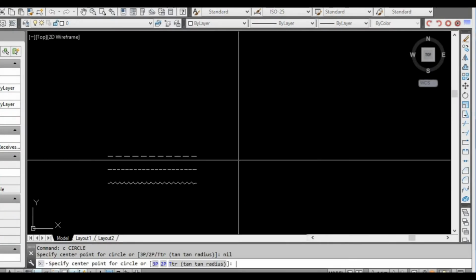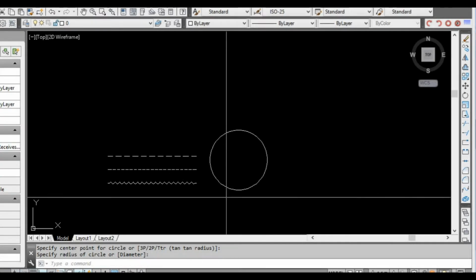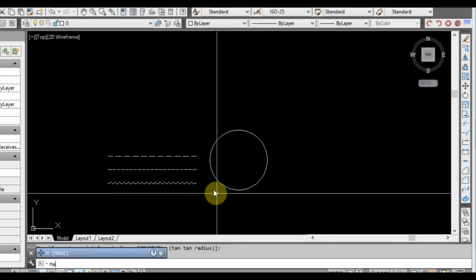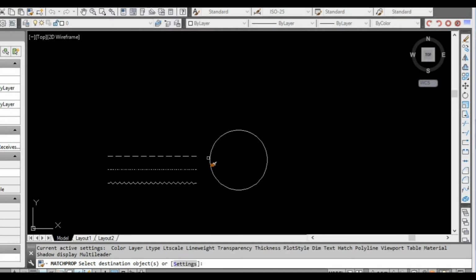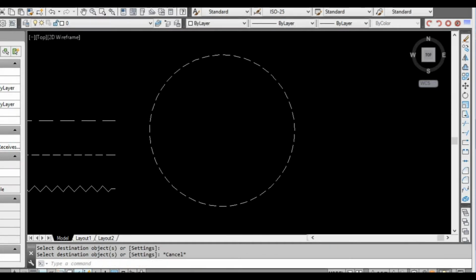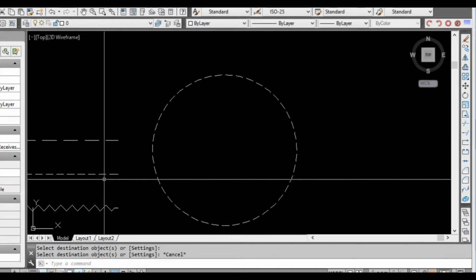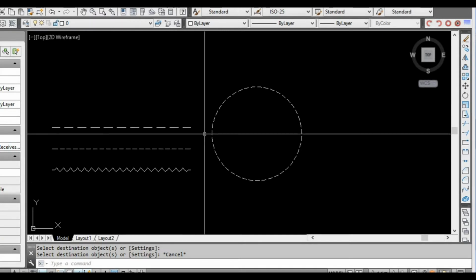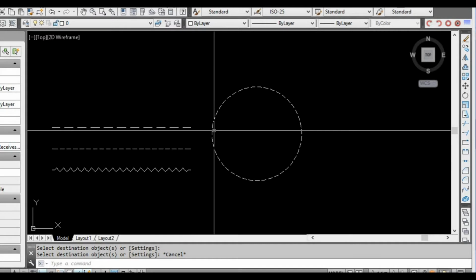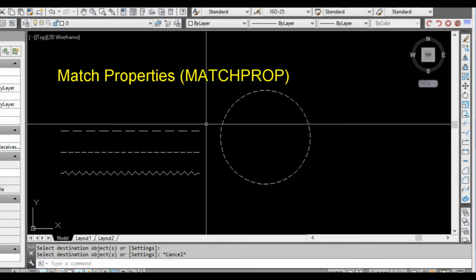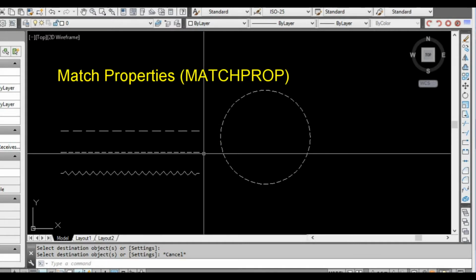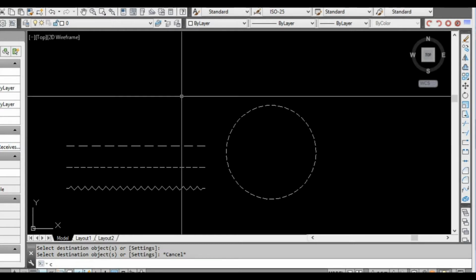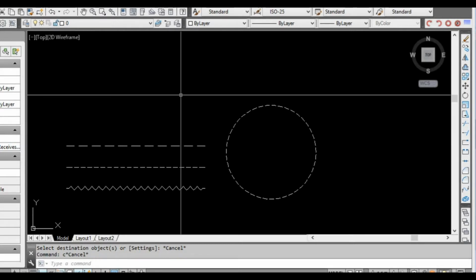So you can do that too on lines if you need to or want to. These line type things that I'm showing don't just work on straight lines. You can apply them to circles. So as you can see, I've copied that pattern to this one. The command that I use to copy that style to this style is a command called match properties, just so you know. So to match properties to anything, you generally press the MA keys and then press space or enter.